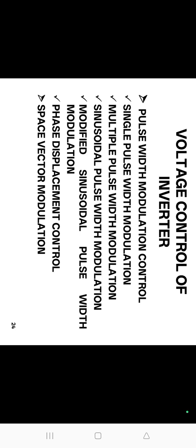The required output waveforms are generated by driving the inverter in 8 unique states. Digital circuits are used to implement the SVPWM technique. The control is such that the PWM load line voltages are on average equal to the given reference load line voltages. The states of the switches are properly selected in each sampling period. The periods of the states are selected such that the output waveforms have quarter cycle symmetry. The states of the switches and their time periods are accomplished with the help of the space vector transformation.